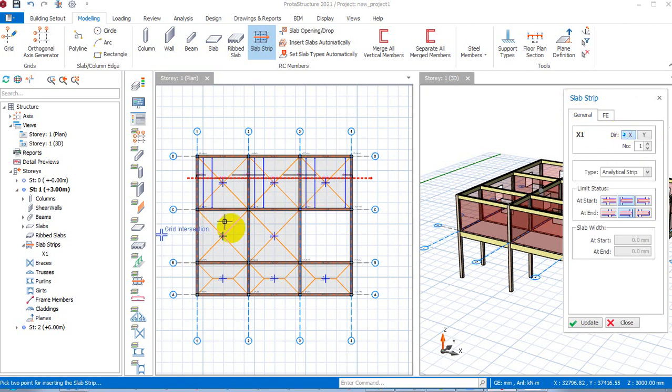Okay, so this is also a beam. This is also a beam. Remember I said this is a staircase area. We assume this to be a staircase. So I'm starting with a beam and I'm ending with a beam. I'll click here and hold down control in order to achieve a straight line. If you don't hold down control, it may not give you a straight line.